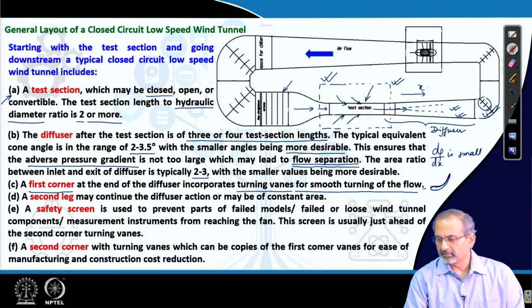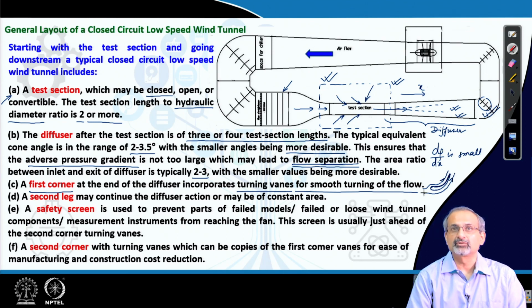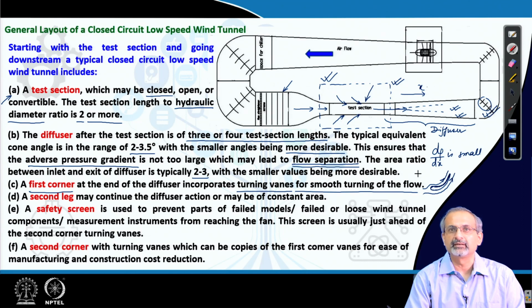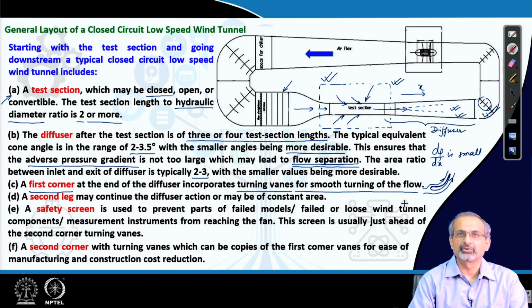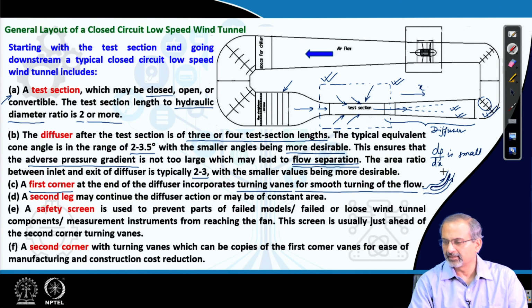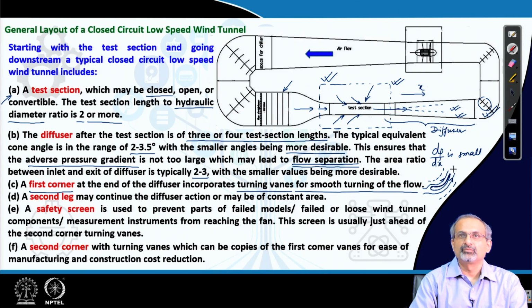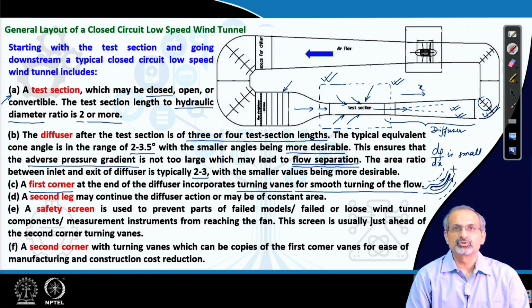They reach out to the flow and make the flow turn smoothly, again ensuring that there is not too high a camber which can induce flow separation. So, that you have a smooth turning, and again remember that there is a cascade of blades. There are adjoining blades which route the flow smoothly through that cascade of blades.